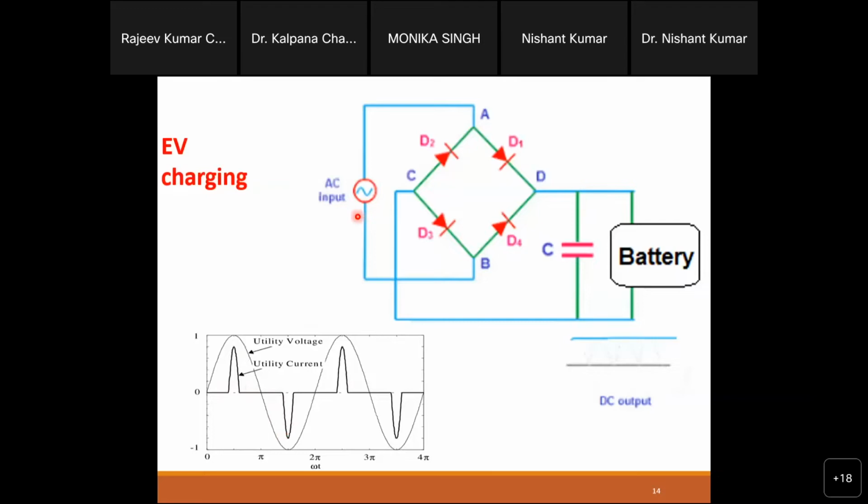In a way, we are intentionally injecting harmonics into the grid, and these harmonics will directly impact our transformers, right? Transformer heating, line side. You will also see an increase in the corona effect, and also some other electronic equipment, because of resonance. It means these harmonics will impact all those components which are connected to the grid, right?